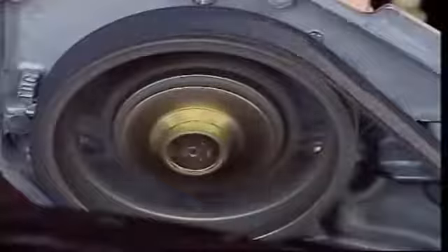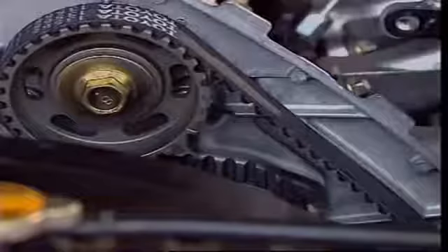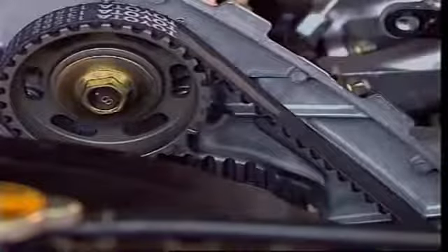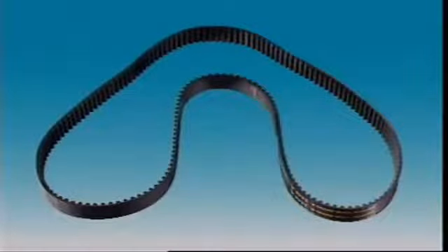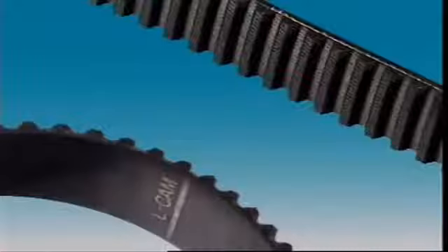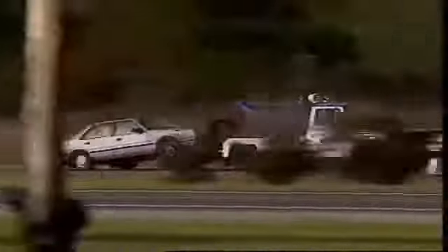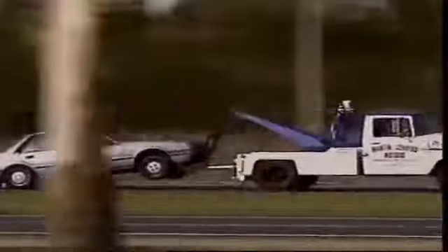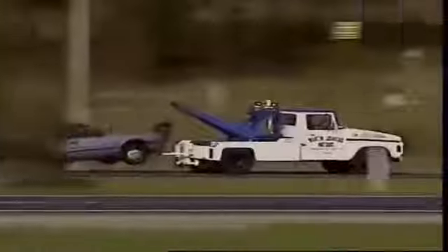The toothed timing belt is made of fiberglass or wire-reinforced synthetic rubber. Its teeth match those on the crankshaft and camshaft pulleys. Timing belts are quieter than chains, but usually require regular manual tensioning. They also have a shorter life than chains. They need regular replacing around 80,000 to 100,000 kilometres. If a belt breaks, it's not only inconvenient, but on some engines it can cause a lot of damage.